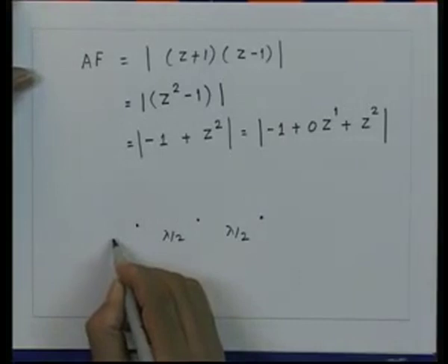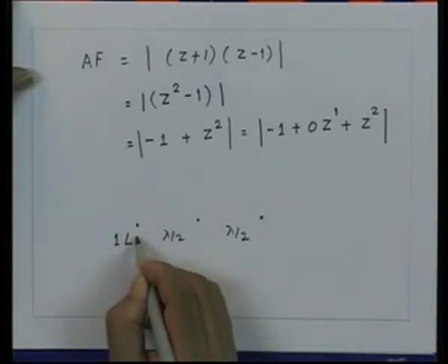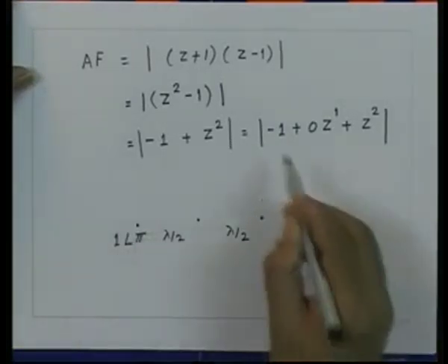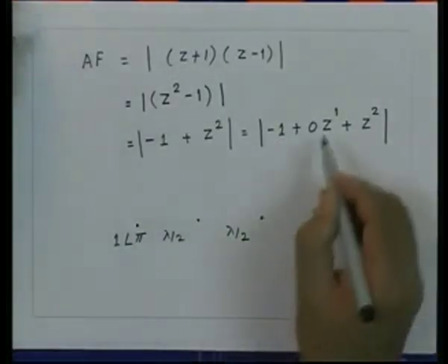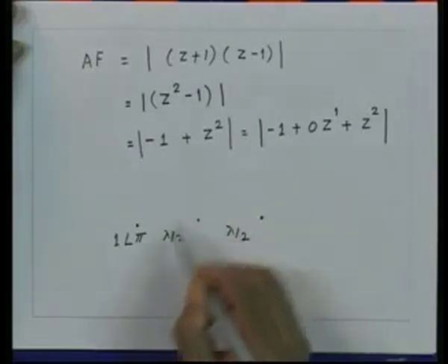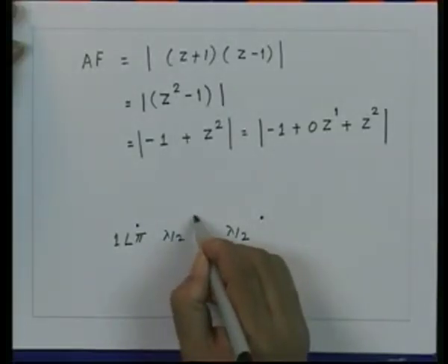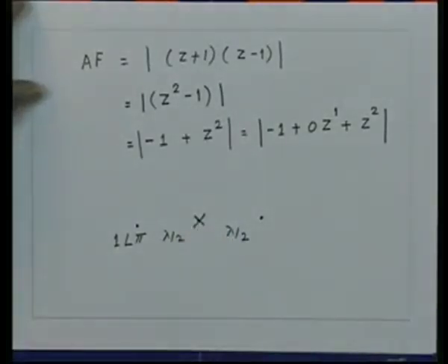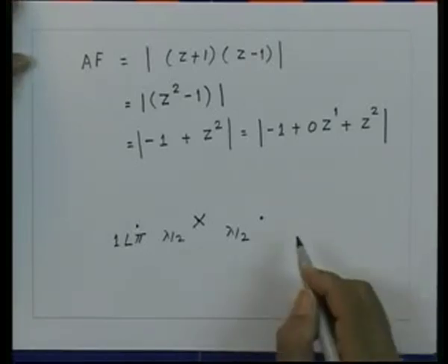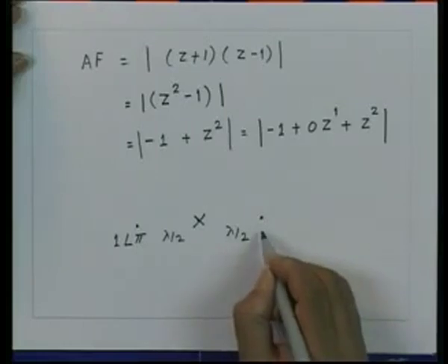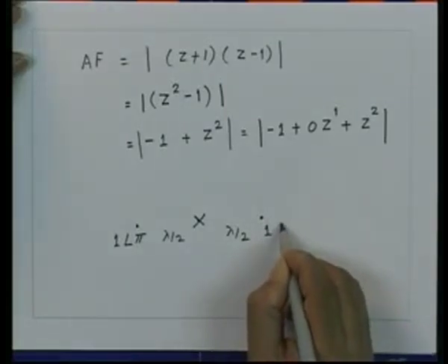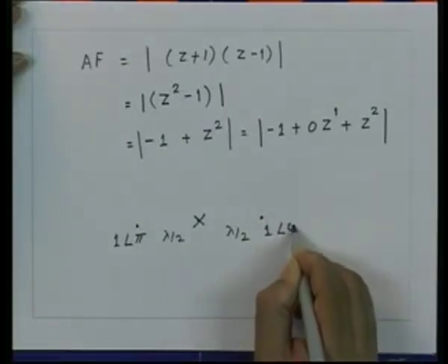So, here the amplitude is 1, angle is pi, that is what -1 would mean. There is no current excitation for this element. So, this element is 0. So, this current element is not there, and this will have an excitation which will be 1 angle 0.